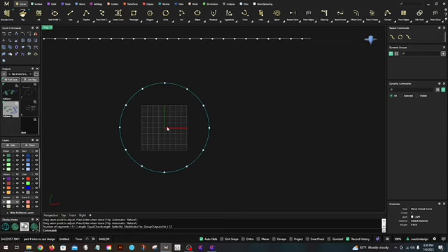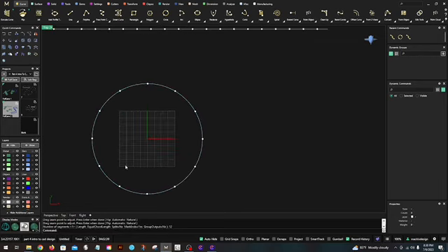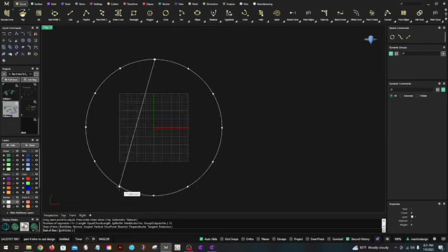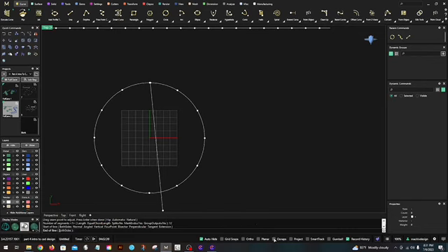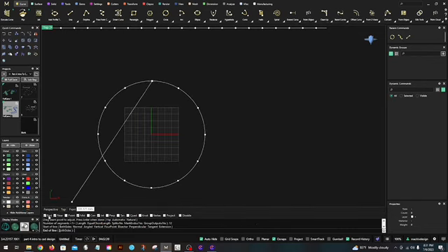There you go. You want to divide this curve so that you can snap lines to it. So in your O snaps, when they're on, you're able to activate different snaps, and one of them, you could do quad, you could do point.